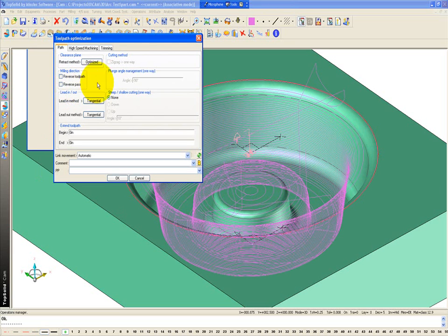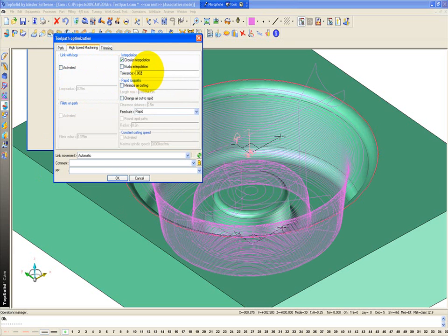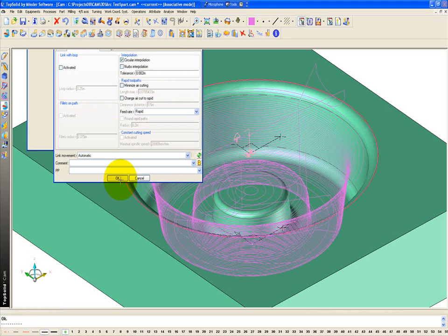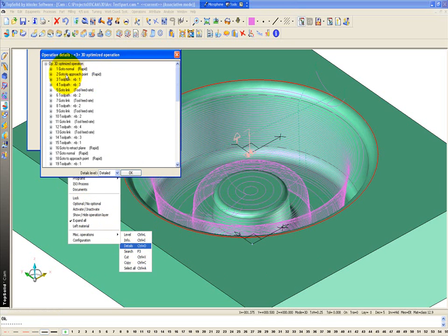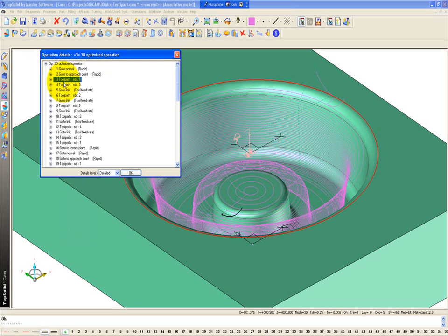Let's see if we play with that, what happens. So here, I'm just going to double the tolerance. Okay. We'll let it filter. And now let's go to Details. So again, we're coming down. There's our arc move on. Here's that first toolpath. And now we're cutting that big circle, a little circle there, a little line segment. Then we're moving over. Circle, complete circle, little line segment. Okay, so this filter will actually help output arcs.